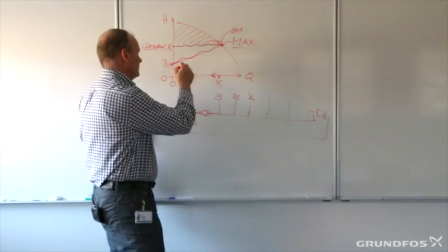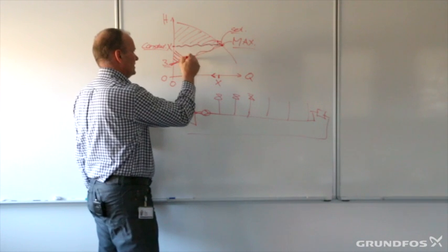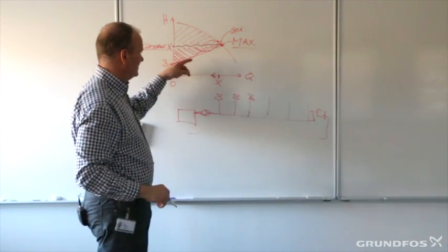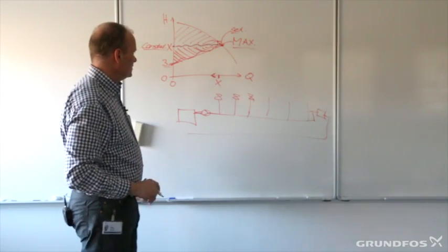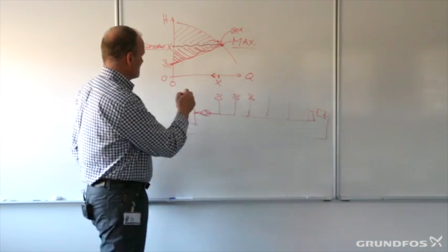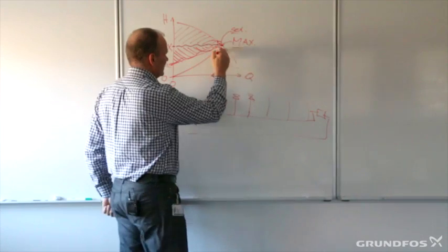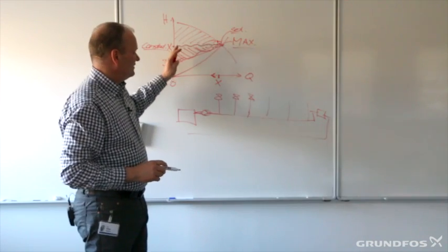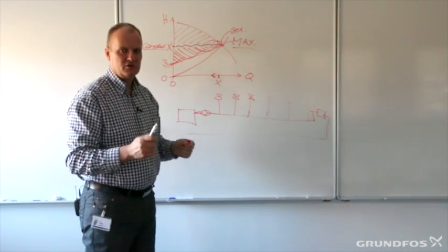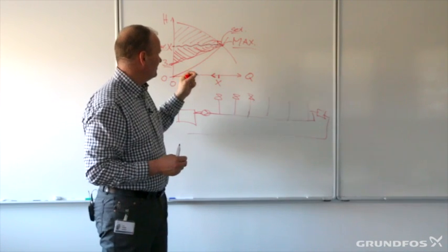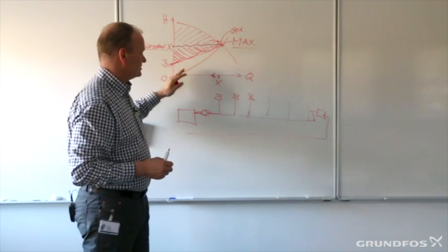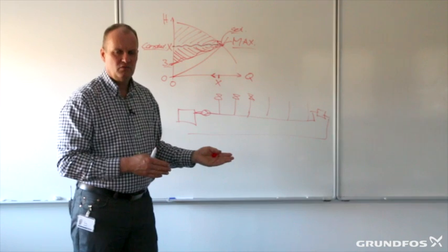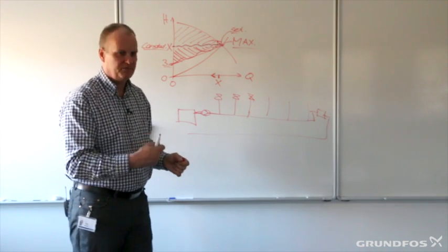And a way to show that is that, okay, when we operate the pump on proportional pressure, then we have an additional saving. So what you can see here is that when we have the system characteristic and a speed control pump, we are much closer to operating the pump according to the system characteristic compared to what we did while we had the fixed speed pump.